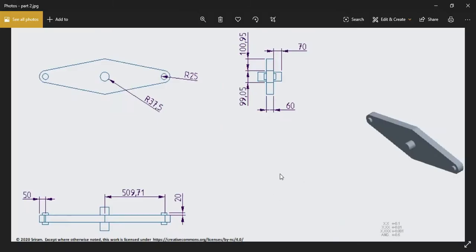Okay, now how we can do this one is, totally the length is 509.71. That is from the center to the center where the 50 radius circle would be constructed. This smaller circle is 25 and this larger circle is with the radius of 50. So from this center point to the center point of the circle, the total length is 509.71. So similarly here 509 and here 509.